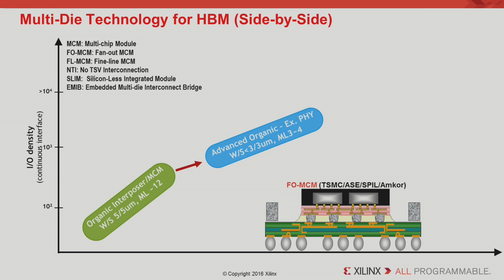So if some folks are concerned about the yield loss on these fine line RDL layers, the other approach is that these layers are patterned on a temporary carrier, and you use microbumps instead of vias to interconnect them to the RDL layers. And then you go through the underfill process, and that structure is then bonded by C4 assembly to the substrate. So that's the RDL-first approach. These options are all going through some level of R&D currently as well.